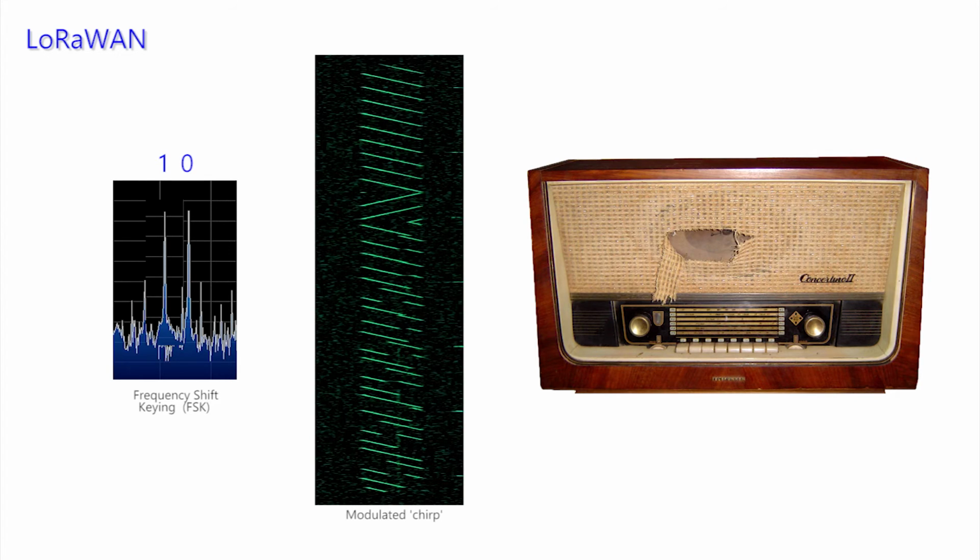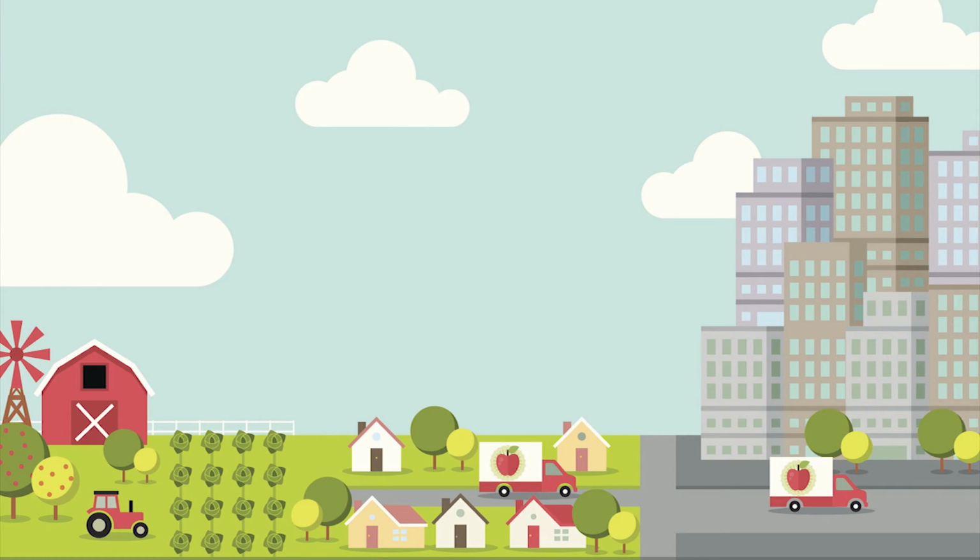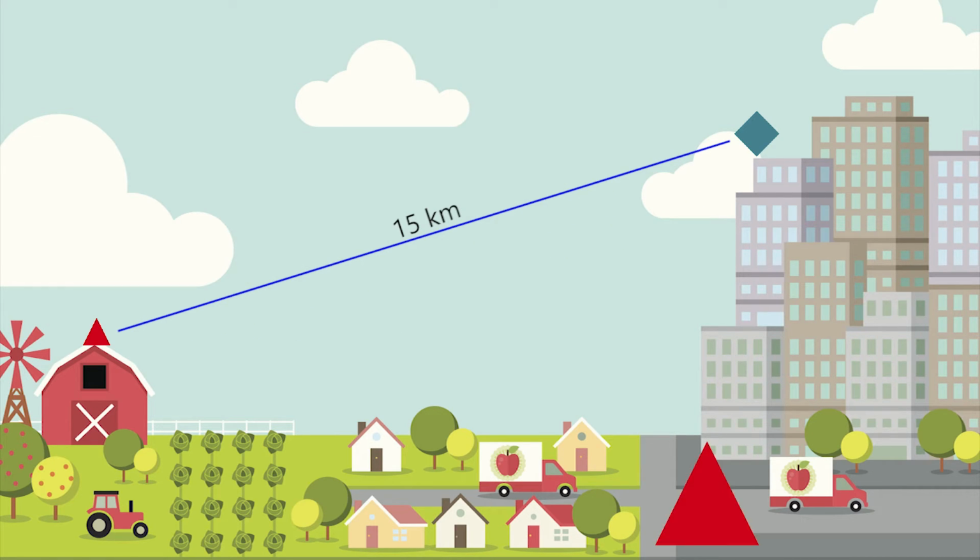1s and 0s are transmitted as interruptions in the normal cycle of a chirp sequence, as seen here. It becomes quite complex, but when used has the ability to hide, but can be seen clearly with a suitable receiver that becomes blind to the background noise. It's likened to conversing at a noisy party. LoRaWAN is built upon this ability, allowing devices to communicate over distances up to 15 kilometers in rural, quiet environments, or down to just 2 to 6 kilometers in noisy city environments.